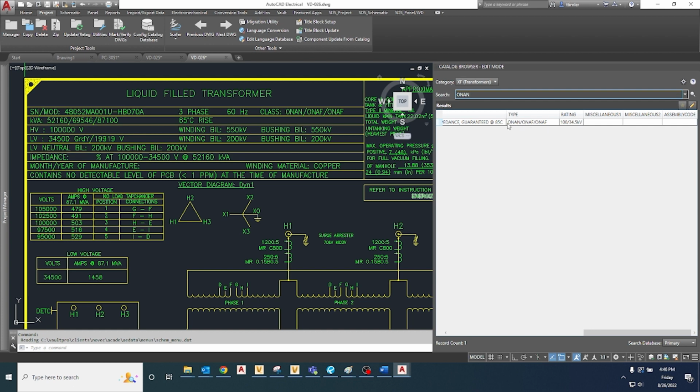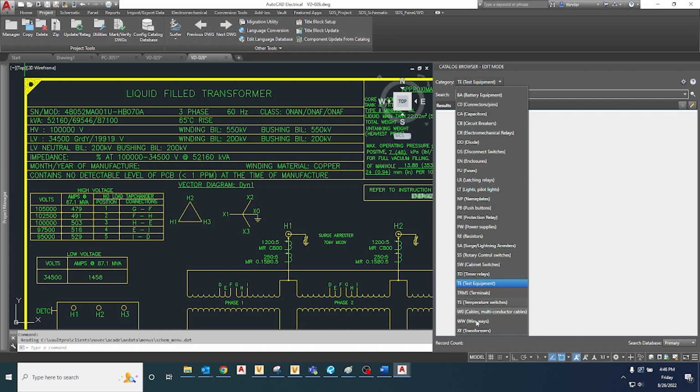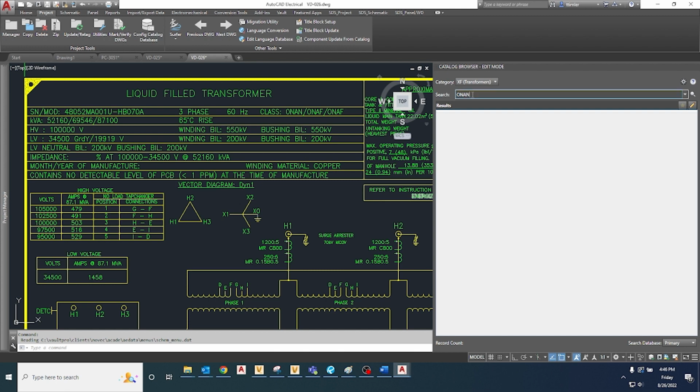When I created the parent symbol, I placed the term attributes in such a way as to keep the catalog coil pins entry the same format, regardless of the term attribute placement. The pin list field is typically associated with child symbols, so I won't be filling this out right now. However, when I come back to this and other entries in this catalog, this is where I will place normally open and normally closed auxiliary contacts based on the vendor prints. This will allow the user to keep track of all available auxiliary contacts associated with this transformer.